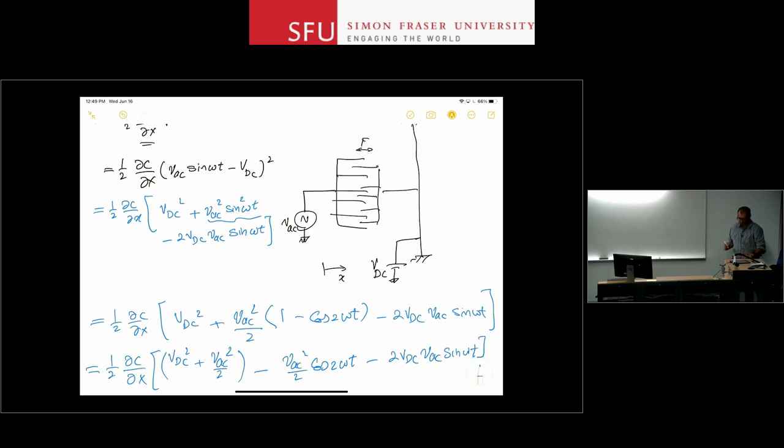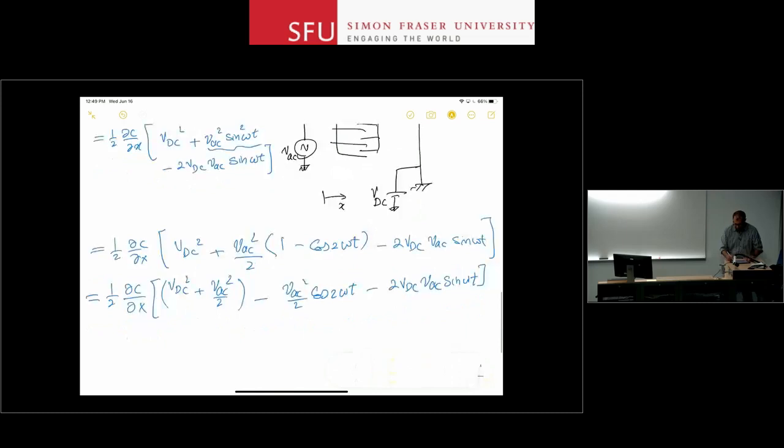Okay? So if you look at this term, you have one portion that is happening at DC, one force that is happening at 2 omega, and one force that is happening at omega. So you have 3 forces produced at different frequencies: a DC force, a force at 2 omega, and a force at omega, right? And the question here is focusing on the signal at the resonant frequency.